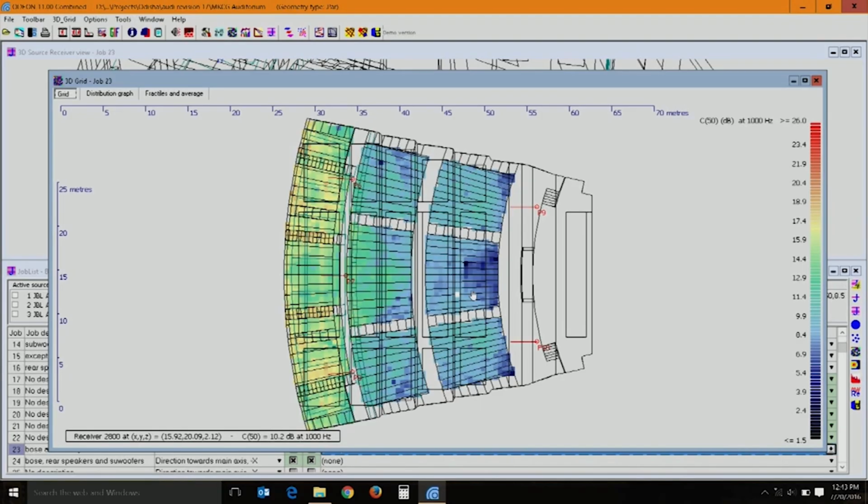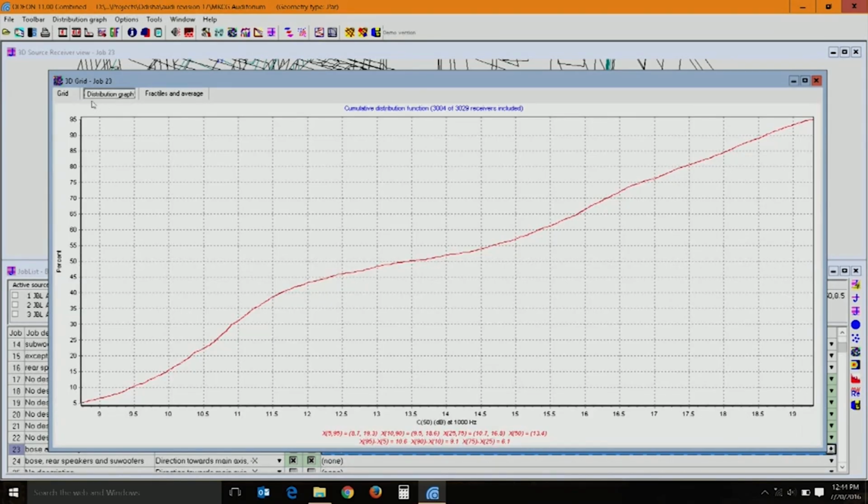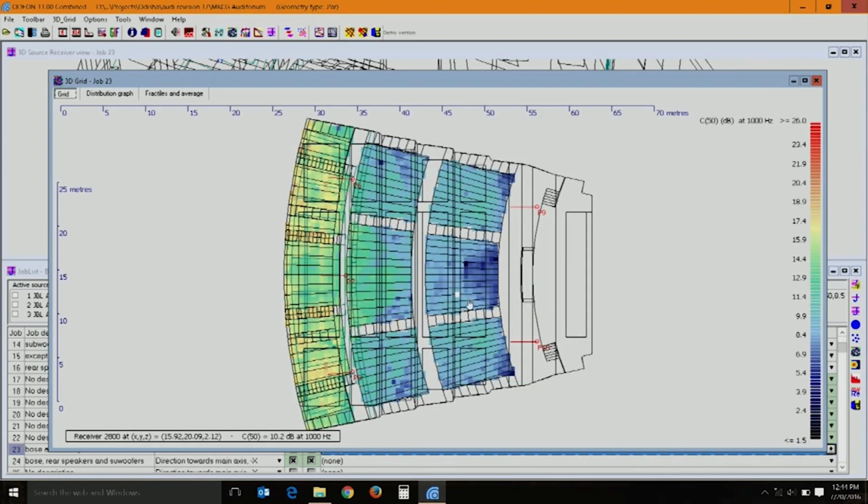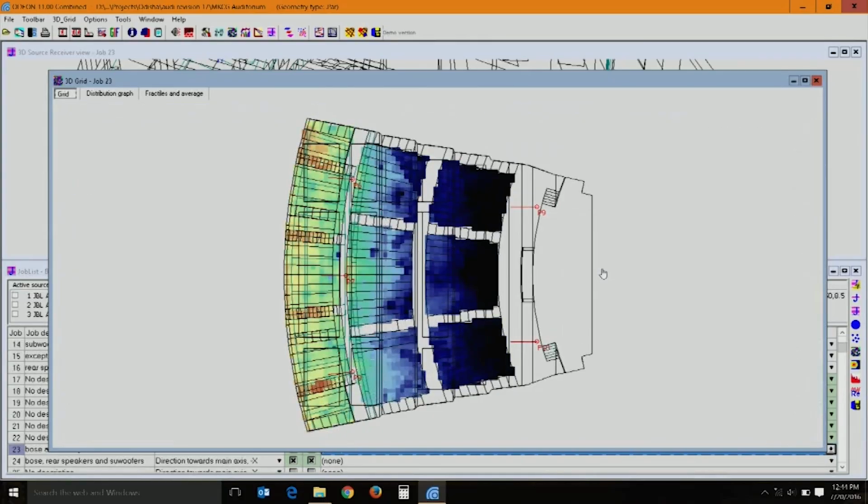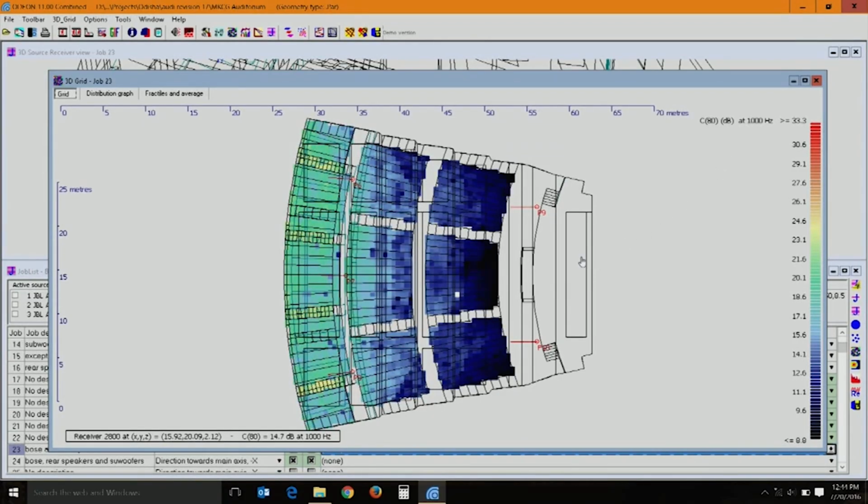We have to try and maintain uniformity. According to that, if you go by that notion, then ideally we will have to bring down the value here, maybe introduce some reflective components or reduce the absorption here, volume you cannot naturally change here. So, eventually you have to get the distribution more proper, this kind of distribution may not be very preferable. So, the clarity part has to be adjusted. Again you can look at different frequencies. So, if you look at C80, initially in this part you have a different clarity, eventually it varies and then it goes up pretty much higher here. So, this indicates that there is a reworking required in terms of clarity.